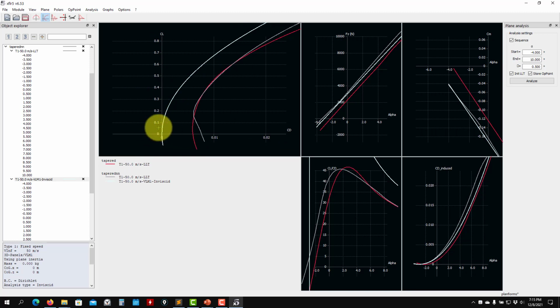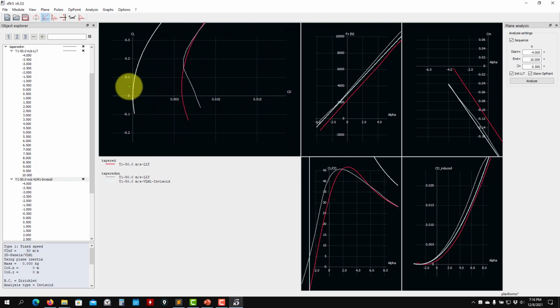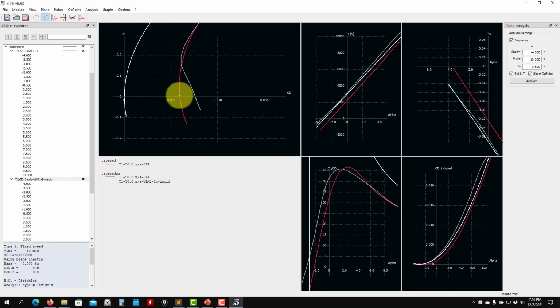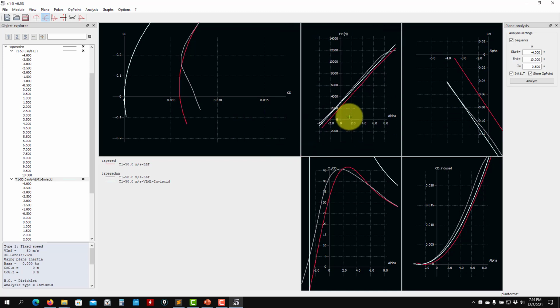Remember here we don't have the viscous component. So you can see here that this is a correction. It's a CD0. Recall from the equations, the polar. You can just shift this one by a CD0, and very often we know that value. You know your clean wing has a CD0 that you computed when CL is 0. At CL0, the drag is all skin friction drag. So you compute it at CL0, shift this curve, and you are done. Very similar results.